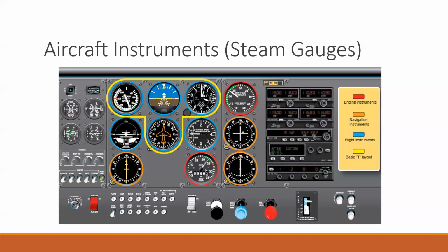Inside the altitude indicator, it has a pressurized bladder that is pressurized to a certain altitude. As the pressure changes on the static port outside, it calculates through some gears and other mechanisms the difference between those two pressures, and it gives you an altitude reading.